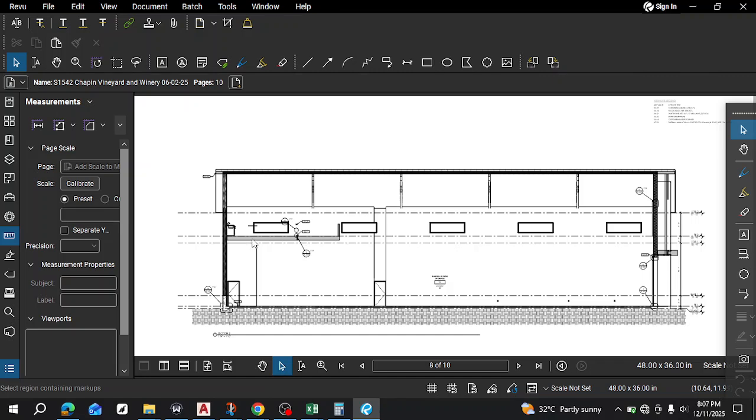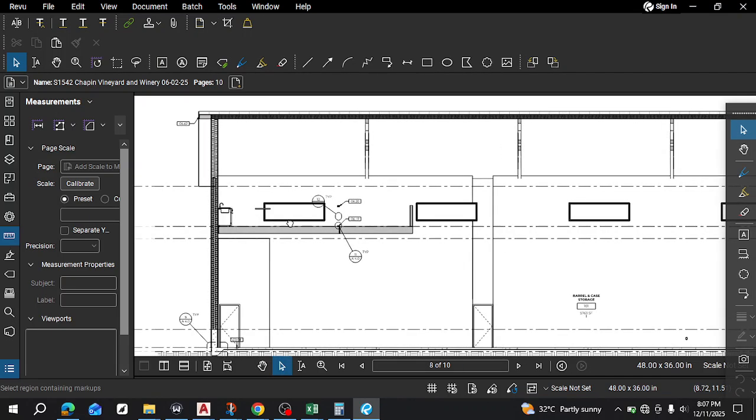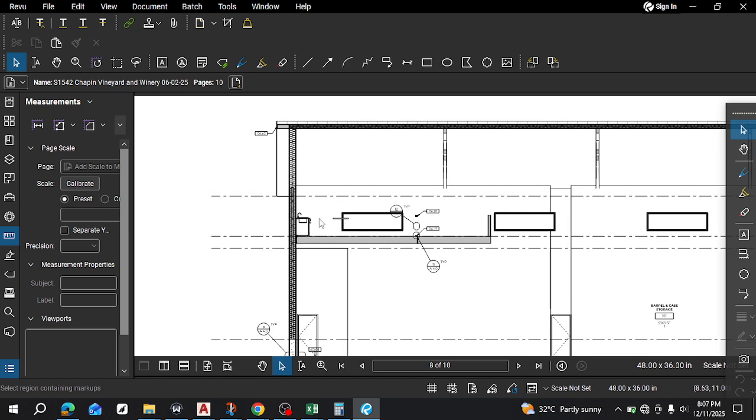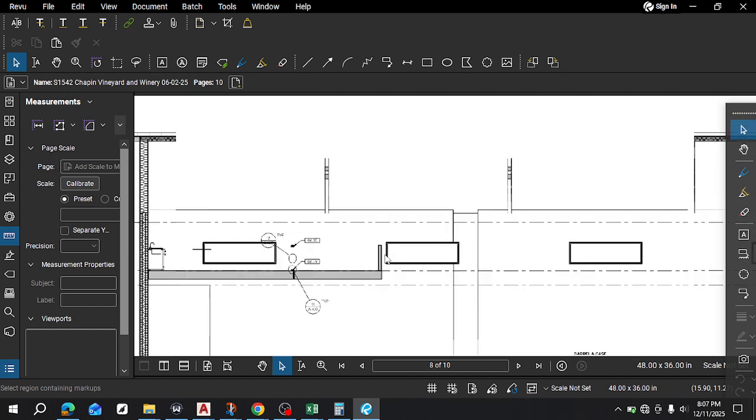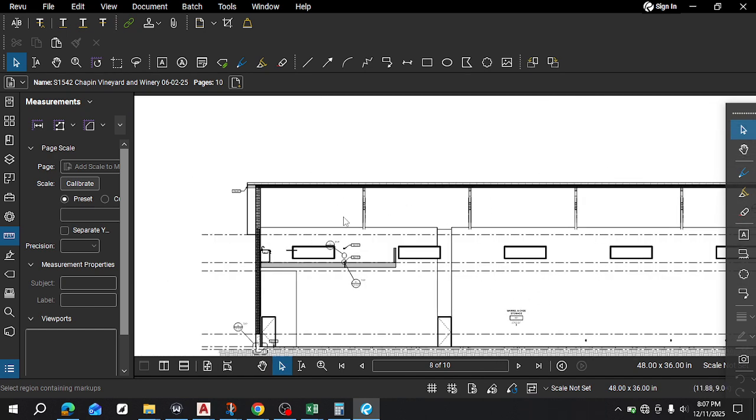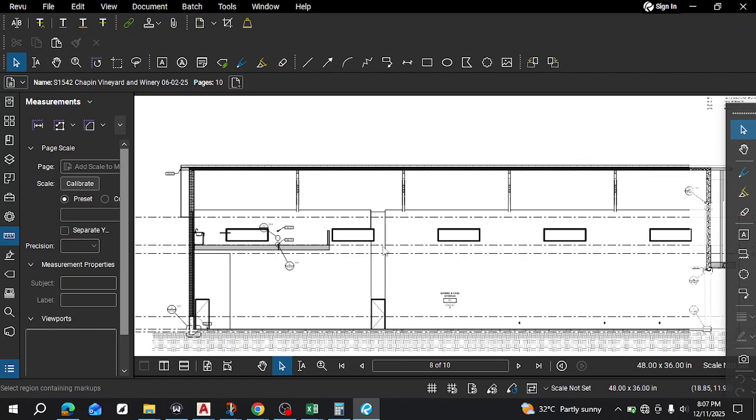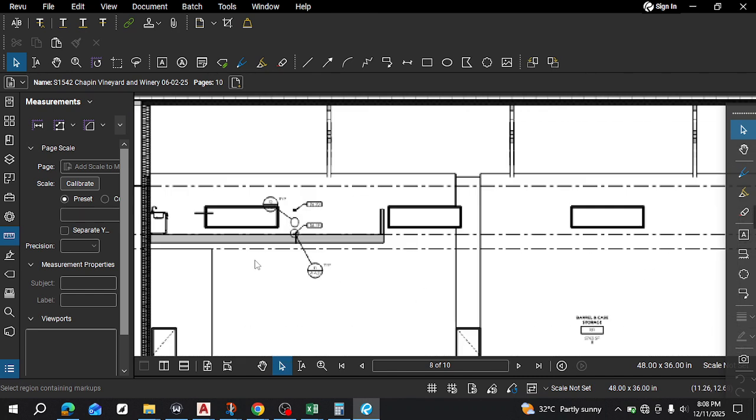This is another section on the side. So this is the entire floor area, and then this is the mezzanine floor. It's just a small section at one end of the building. And we would have expected a wall, but there's no wall. So that means it is still treating this whole space as one uniform space. The only time we can treat it as different spaces is if there's a wall separating. So the air is uniform around here. So any conditioning we are doing is treating this as one space, which is one zone, right?